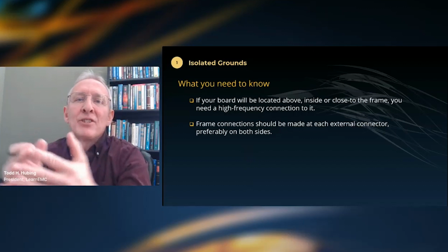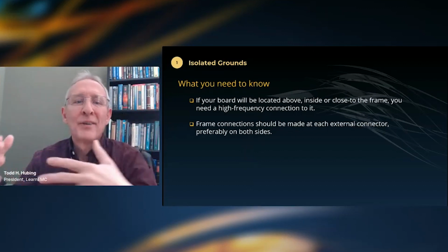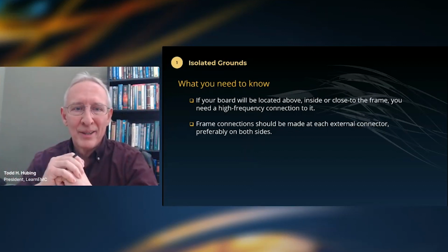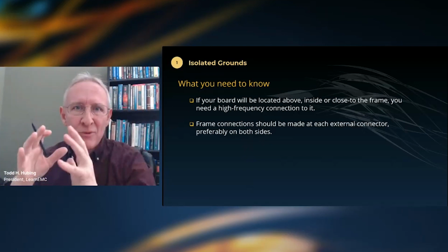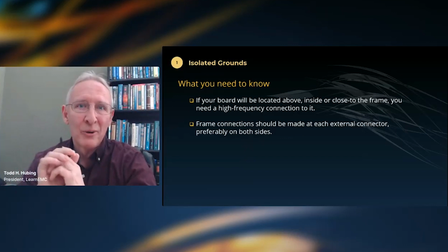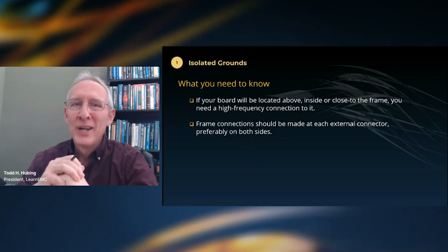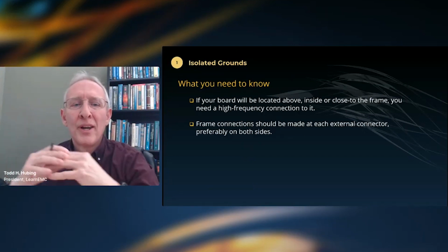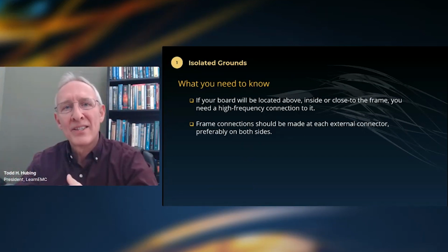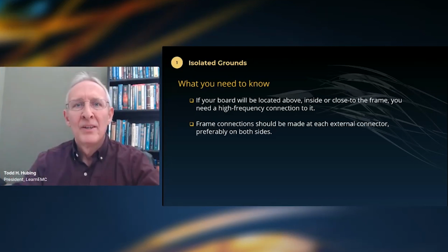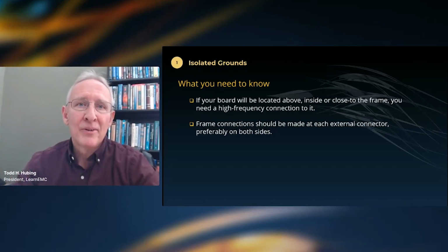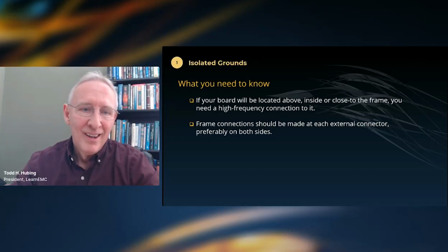So we don't have time to talk about everything you need to know about grounding in this talk. But I wanted to boil it down to what you really need to know. And what you really need to know if you're laying out the board is there is a ground. You can't ignore it. If you're designing a circuit board, everything that leaves that circuit board that's large and metal needs to be bonded to the ground or shielded.